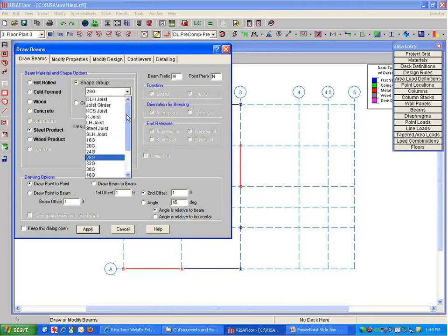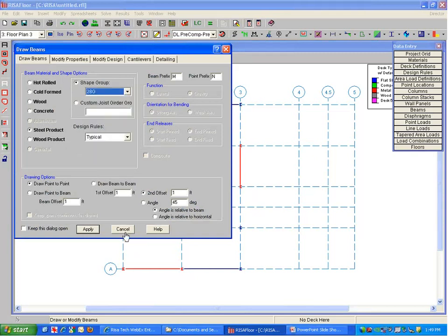You could tell the program here to choose just joist girder, but it's going to size it based on the weight. And that's not typically what people do in the industry. You usually know what depth you're going to be allowed for clearance. And so you're going to want to probably set up one of these and not let the program try to optimize on weight for girders. Girders are one of those things where you just always know what your actual maximum clear height is going to be there. So we're going to give it 28 inches depth for the girder.